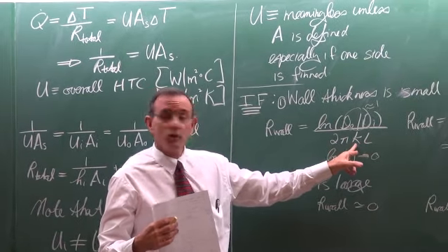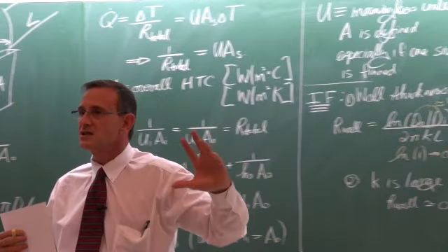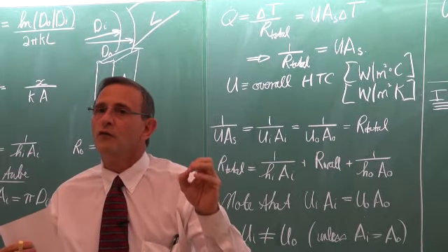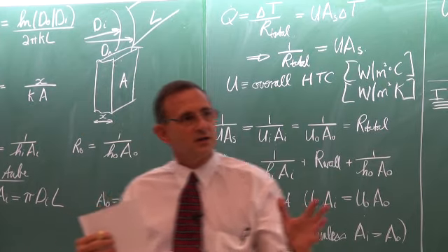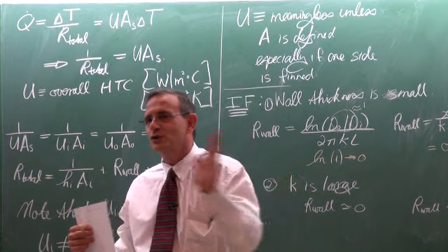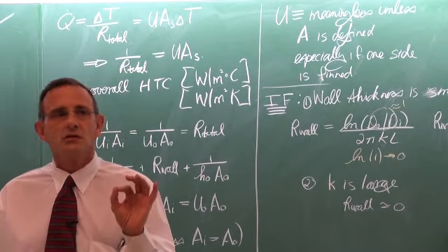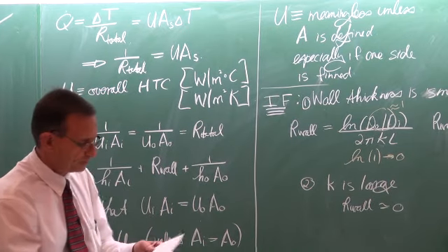So although this is not high, this is very small, and in many of those cases also the resistance of the wall is negligible. So the heat exchanger is not going to be a better heat exchanger if you change it from plastic to copper. Okay, it's still going to operate very, very well because the wall thicknesses are so thin.